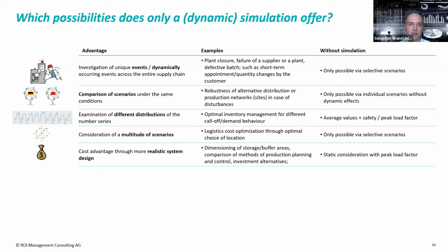The sequence of the car bodies is a high rack with hundreds of buffers for car bodies, and one buffer place for one body costs around €3,000 invest. So if you take 10 more or 10 less, it's €30,000, then it's worth an examination instead of just using a peak load factor.